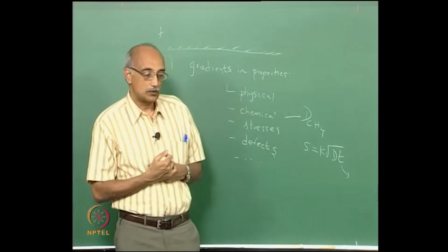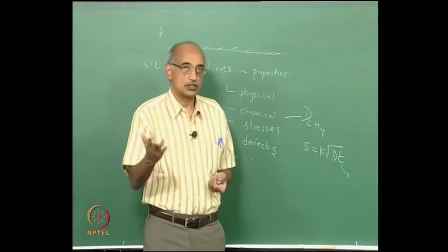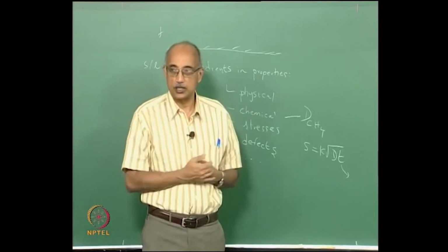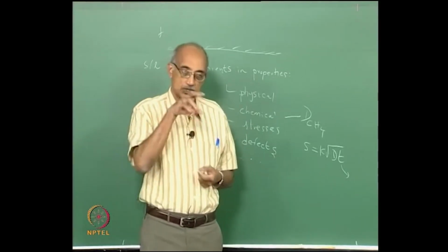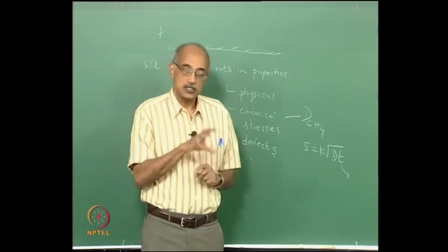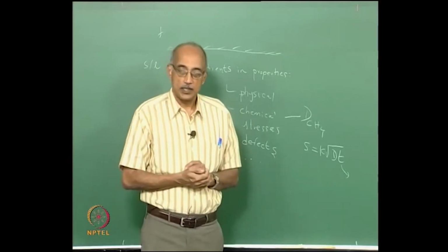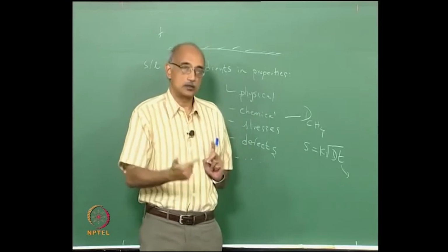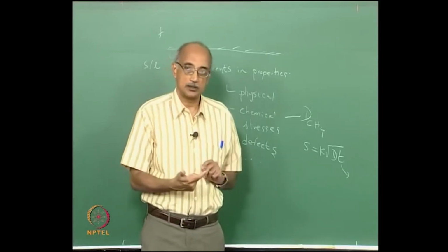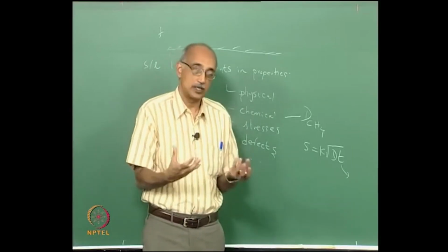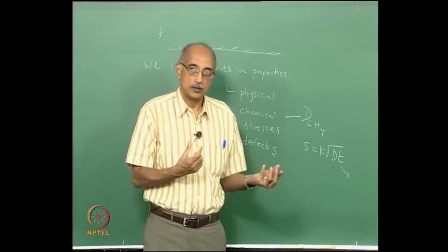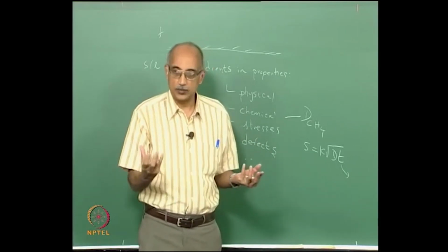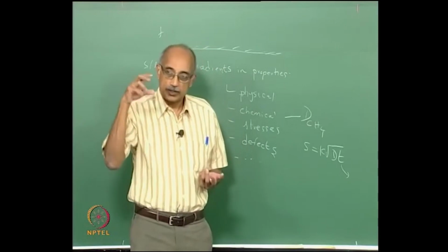But if you now let the penetration continue, let us say that you have a very porous aluminum particle and this oxygen can diffuse into the interior of the particle, then the composition of the entire particle will slowly change, and the particle itself will eventually be converted from an aluminum particle to an aluminum oxide particle